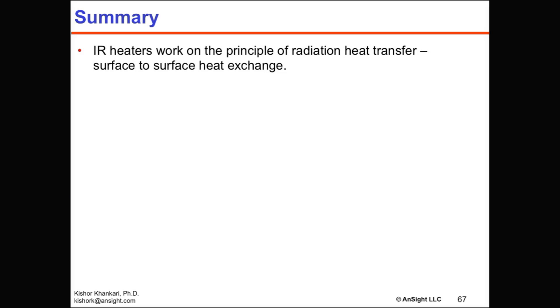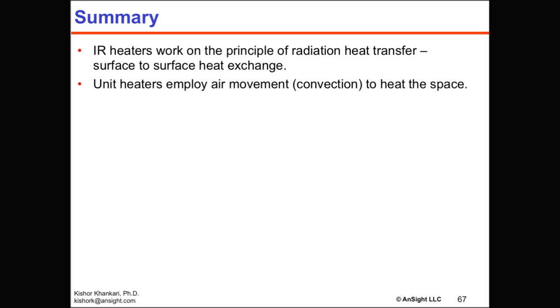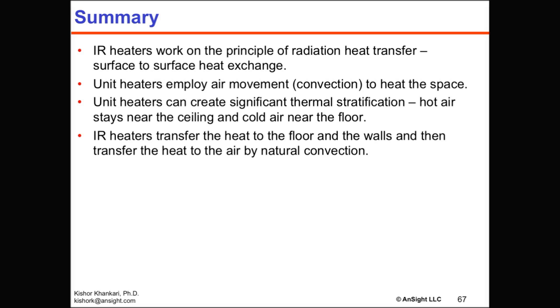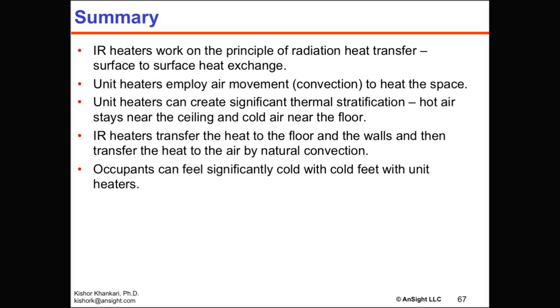So in summary, IR heaters work on the principle of radiation heat transfer. It is surface-to-surface radiation. Unit heaters employ air movement, hot air movement, to heat the space, convection. Unit heaters can create significant thermal stratification. That means the hot air will stay near the ceiling and cold air near the floor. IR heaters transfer the heat to the floor and the walls and then transfer that heat to the air. So all those floors, they participate in the transfer of the heat. Occupants can feel significantly cold with cold feet.